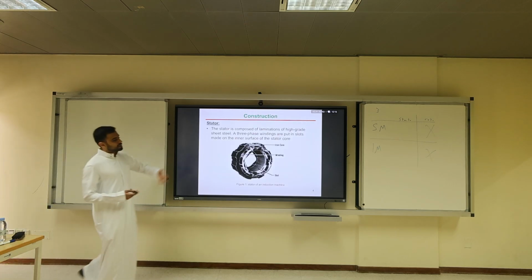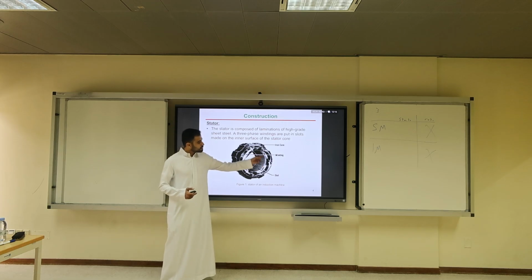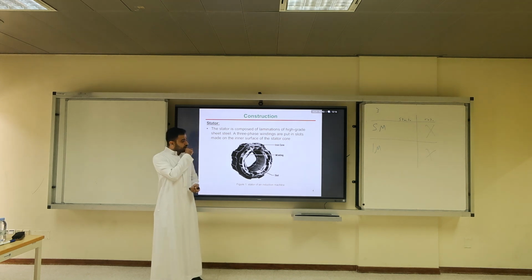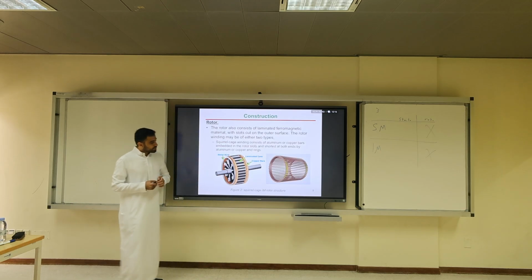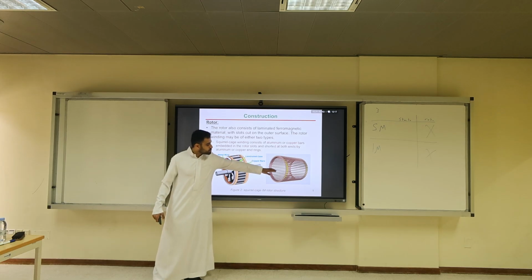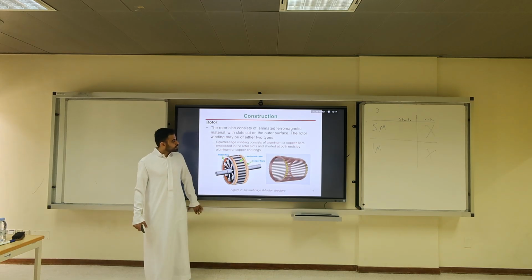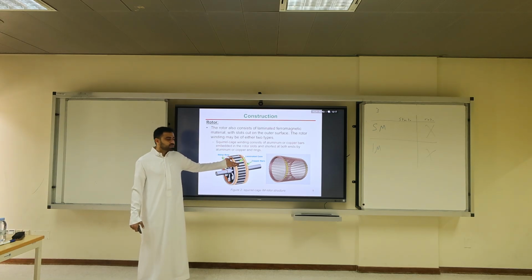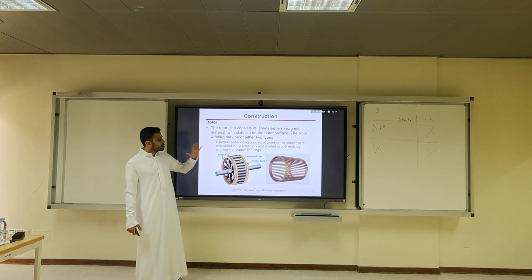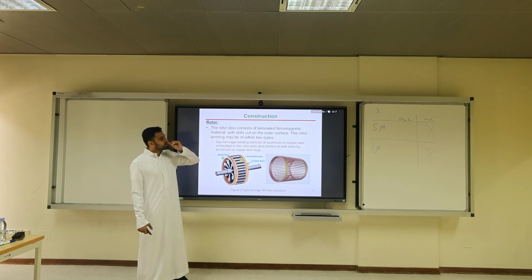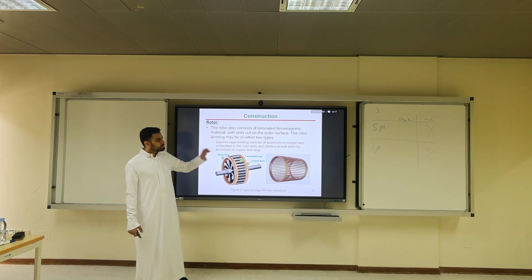So the stator, I already told you it's the same. You have slots, laminated steel, and put the coils inside and connect them to three-phase. Or if it's an induction generator, you get three-phase. For the rotor, the squirrel cage is the most common one. You put the cage above the rotor, and you have copper bars, for example. Sometimes they make it aluminum, sometimes copper. There is no unified design. So the rotor has laminated material with slots, which can be in the outer surface.